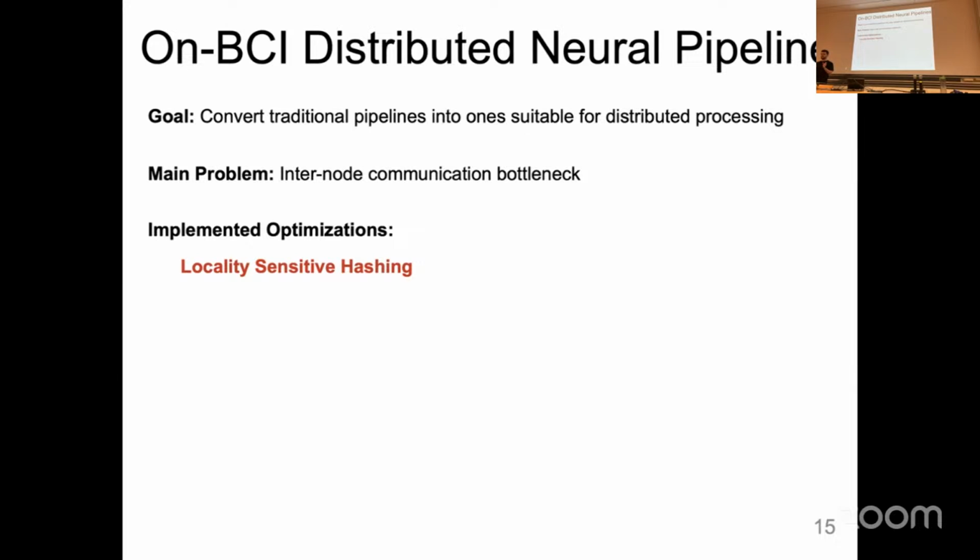So we can compare the hashes in like seizure detection, for example, and still have some meaning to those hashes instead of the usual cryptographically secure hashes. Okay, and then this is how you would imagine, right? You have a signal, you have this LSH function, you pass it through, and you get a hash that is about 100 times smaller than the initial input. And wherever possible, we only send this over the network instead of the full signal. Okay.